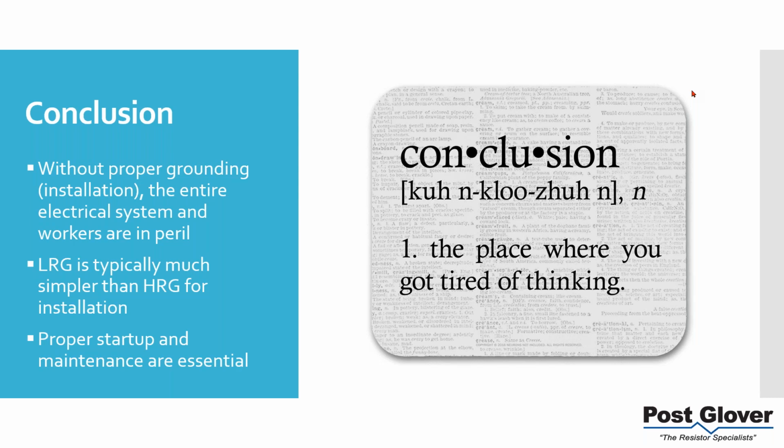It's a convection cooled resistor. Is it possible to do a NEMA 4 resistor? Yes, but you're going to need some kind of forced air situation, where it gets more complicated, with more potential failure issues. So the easy answer is almost always you're going to have a NEMA 3R resistor, but you can definitely get the controls in 4X to make sure that there's no issues with the controls.